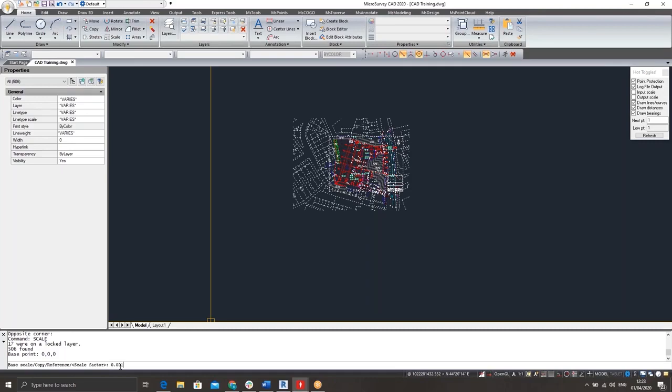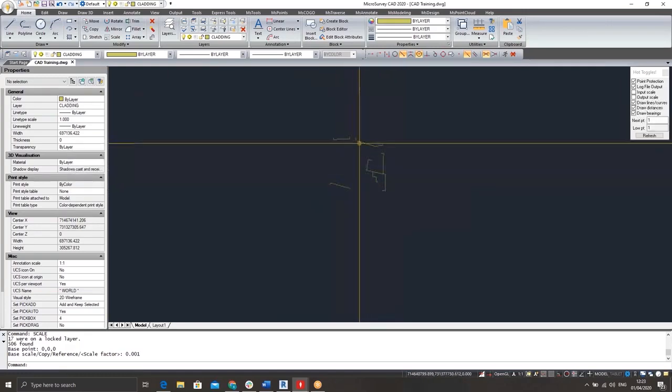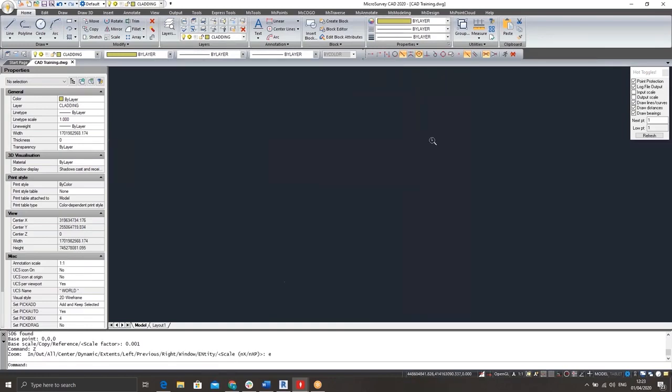because that's how many places we want to move the decimal point, just to make it easier to remember. So if I select enter, we cannot see our information anymore. Some of the information has been left here. So what I can now do is go zoom, Z, enter, E, enter. Okay, and zoom out so I can see a bit of information down here.